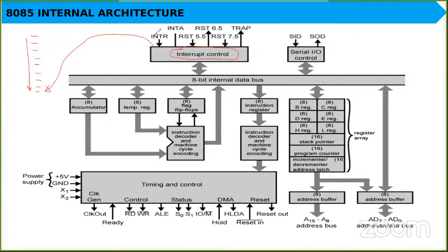The sensor will give an interrupt to the processor, as a result of which your execution will break here, and it will do something which it has to do. We are going to see this flow now. Maybe you'll understand this flow better when I teach you how the instructions actually happen. So an interrupt is required to interrupt the processor.